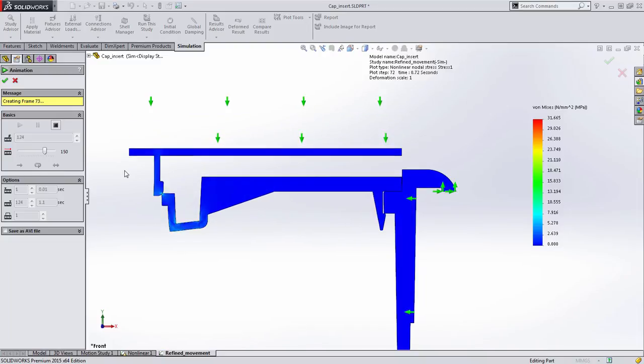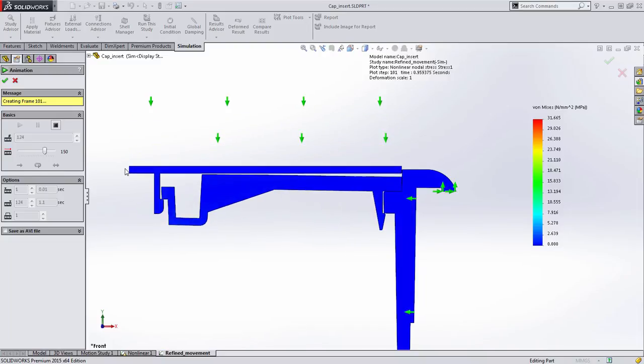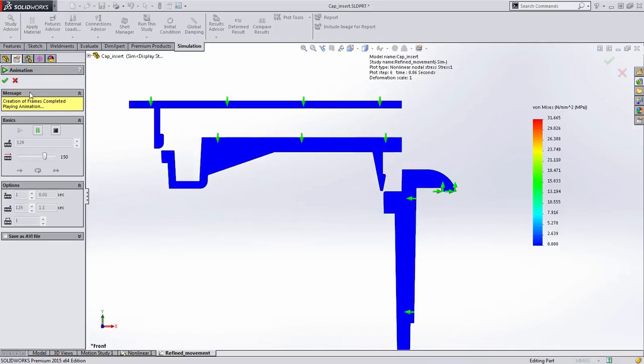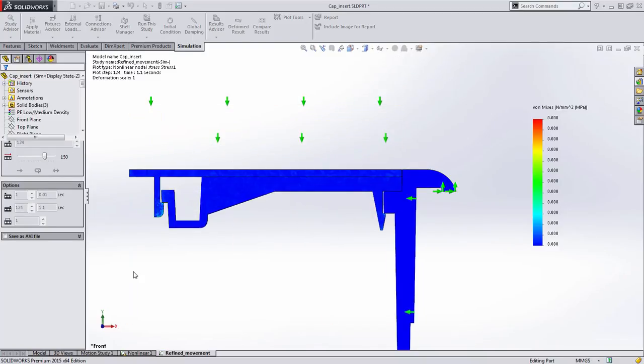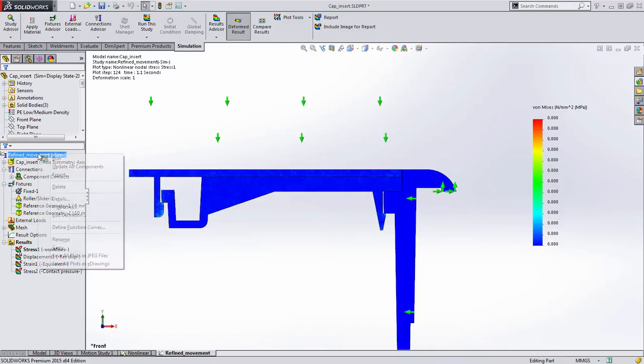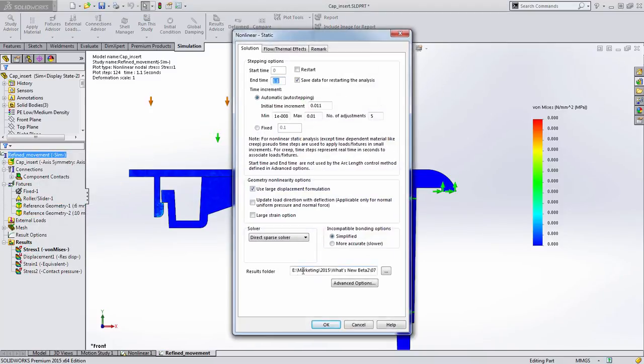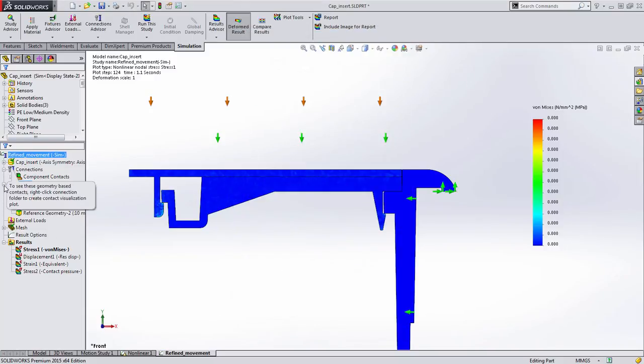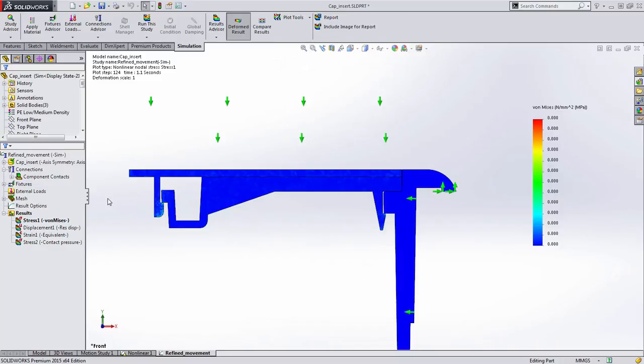And as you probably know, when you're dealing with simulations, it's the path to the results. So if you move them around, you're just going to make sure that you update the pathing. So you go to your properties and make sure that path points exactly to where your files are. But for size reasons, we can't include all the results in the deployed demos.